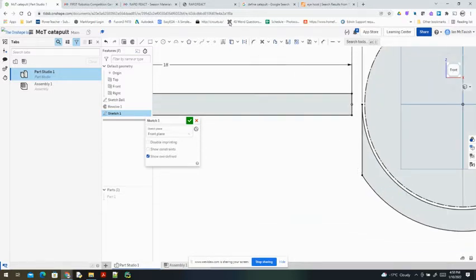So what I'm going to do is add some holes centered on here. So this is where I'll put my bolt, and I always need at least 2 of them. And they're equal in size, so I'm using the equal constraint. And these are going to be 1/2 inch from there, and then that one will be 1 inch. So very standard sizing.